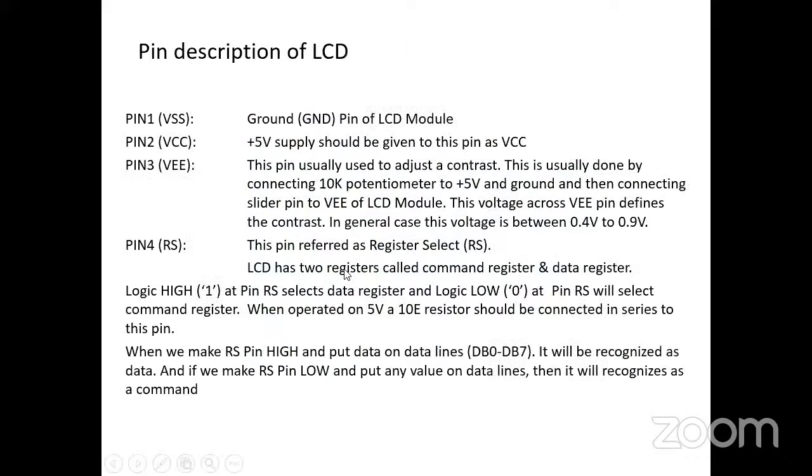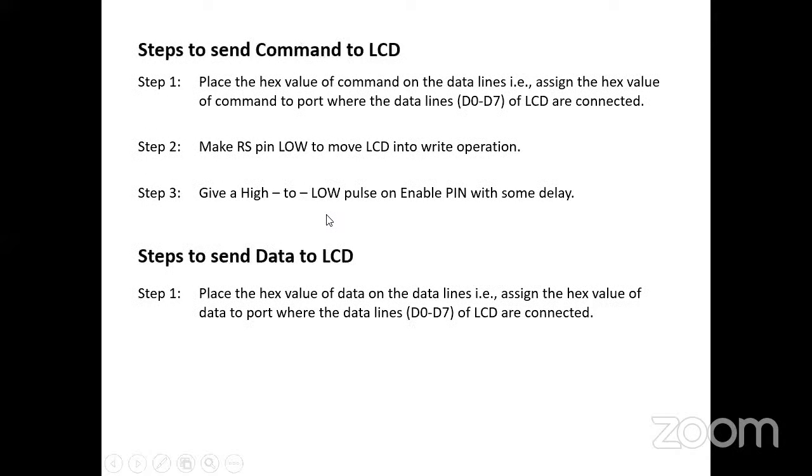Here already we discussed this one once. How will the LCD work? First we will provide the command on the data lines, then we will provide the data. Here in the LCD pins, we will provide the command, then we will provide data.